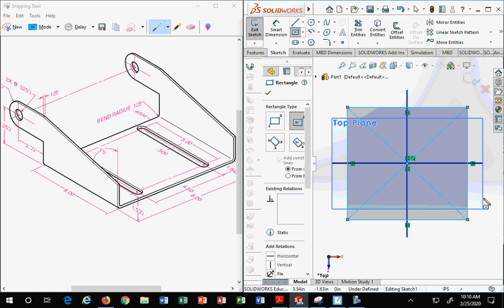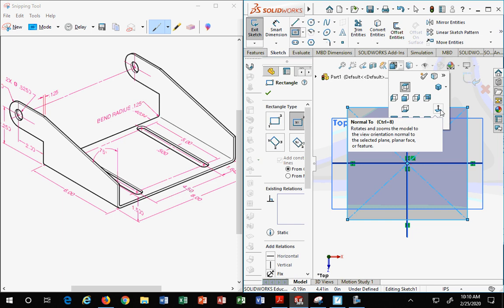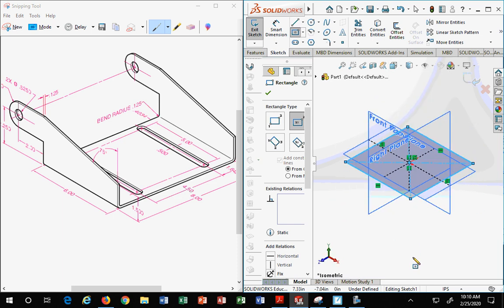It'll be recorded for the 1,000th time. I'm lazy. If I can save myself some work later, in this case adding planes in to use the mirror command and whatnot, I'm going to do it. So if I use center rectangle, I have that option. I don't have to create a plane later to mirror my one wing over to the other side.